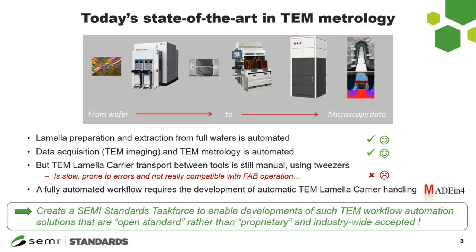Today, lamella preparation and extraction from full wafers is automated, and also data acquisition and TEM metrology is automated. However, TEM sample transport between tools is still manual, with operators using tweezers to manipulate the very fragile lamella carriers. It's slow, prone to error, and not really fab compatible.